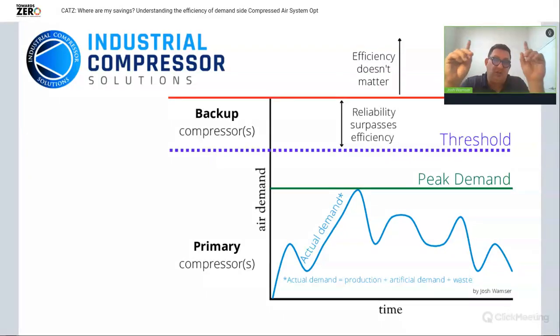Now, if we do that, my question to you all is, how close to that threshold line are we, and how important is that number? In a small system like the one we saw with 109 CFM, how much of the time are we spending within 10%? How much time do we have before the system expands to where that second compressor comes on? So it does make sense to consider permanent monitoring and measuring that flow rate against the threshold of where that second compressor comes on.